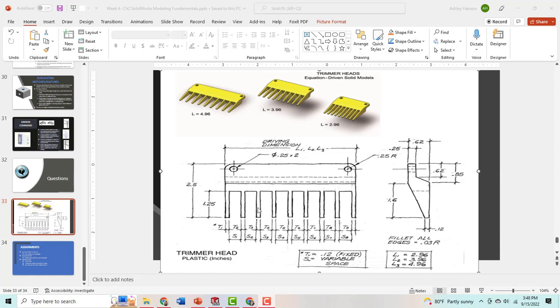All of these hidden lines and center lines you see, you do not need to add to your model. This is what is represented in your technical sketch or drawing when we start creating them. So they are not lines you need to add in this sketch. Also note that you need to use your entire height of 2.5 to define this right profile sketch. This part is going to be built in inches, and we're going to start on the right plane for our right profile.